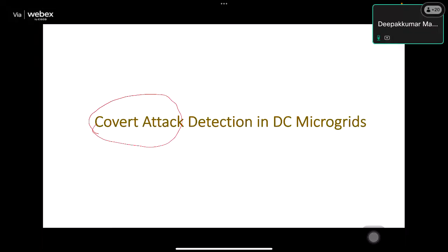These attacks actually happen in a way so that they remain hidden. Now I will also explain the principle. Suppose my pure control is up and the actual control is u of t. If I add a very small value ua of t, it will never saturate. Then it's very difficult for me to detect that there is an attack. So it always remains hidden.